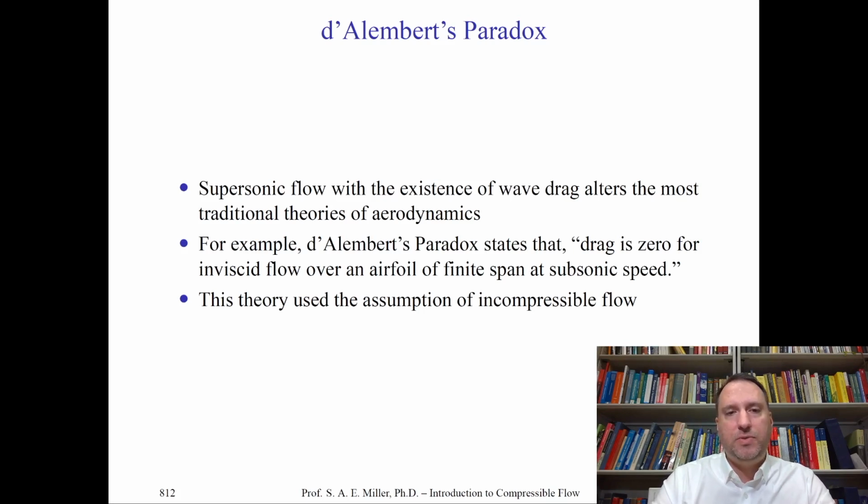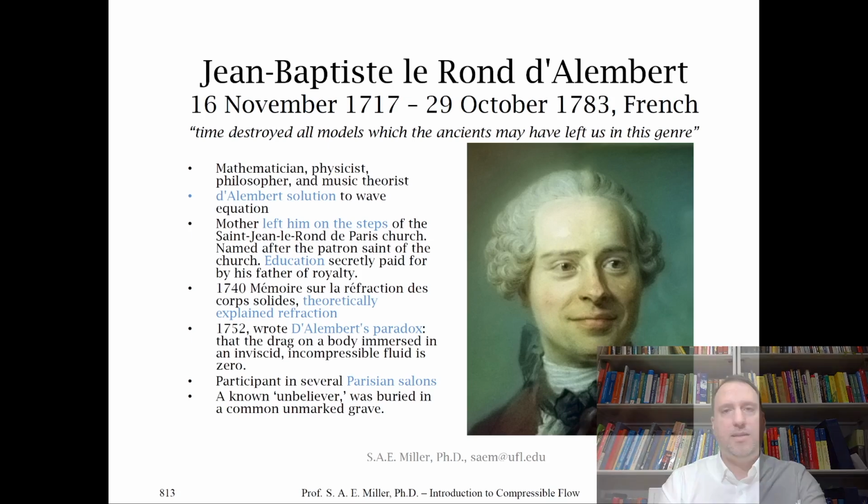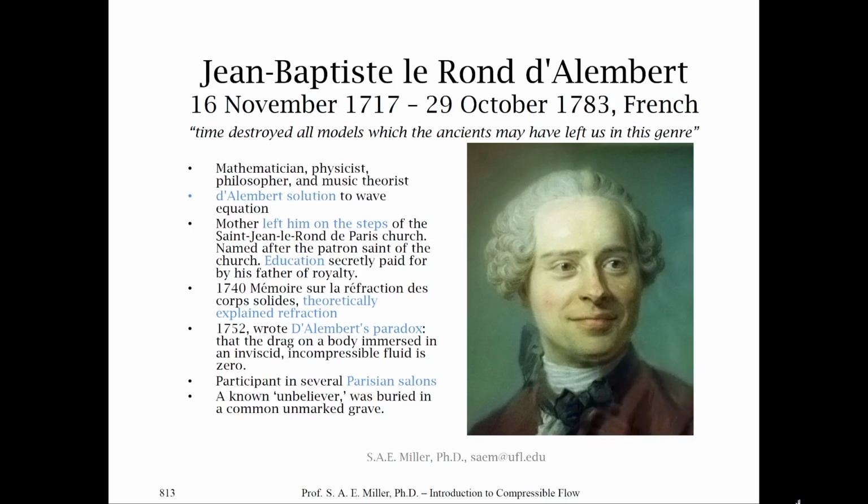Now, this theory, which we just used in D'Alembert's paradox, made the assumption of incompressible flow. Here we made no such assumption, and say a finite span airfoil at higher speeds will have these discontinuities, and we do find a drag, which is the wave drag. And so in some way we have resolved D'Alembert's paradox by including the effect of compressibility and the theories of Prandtl-Meyer.